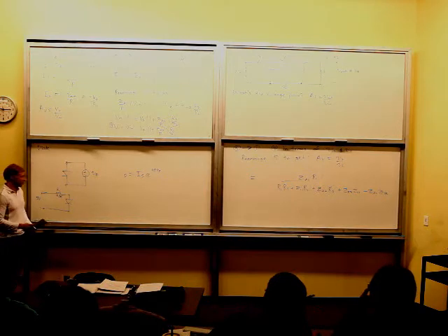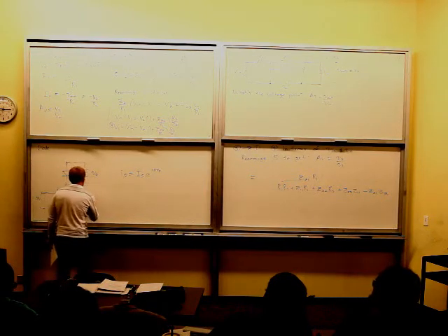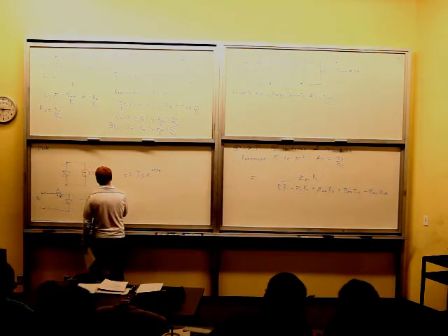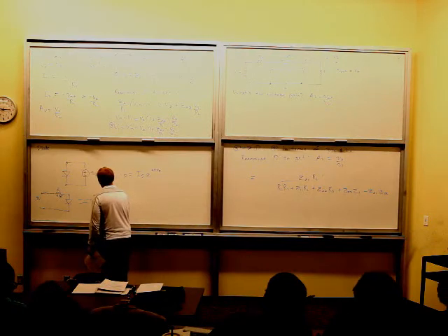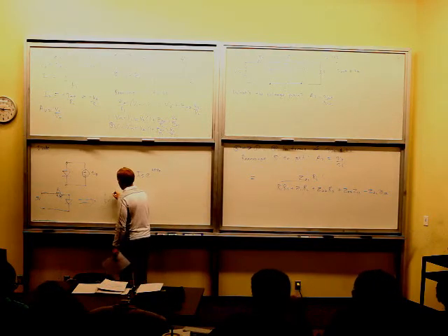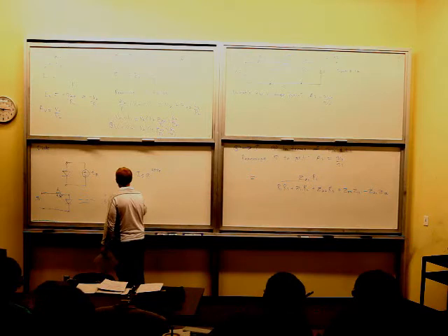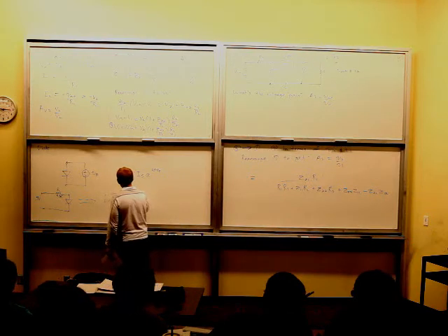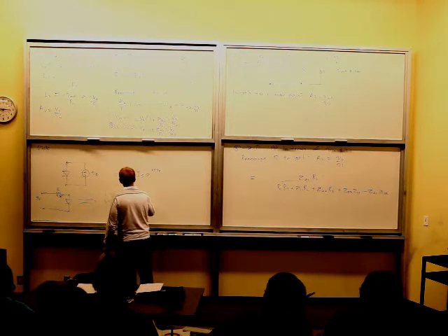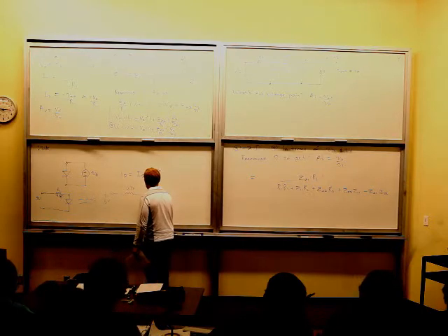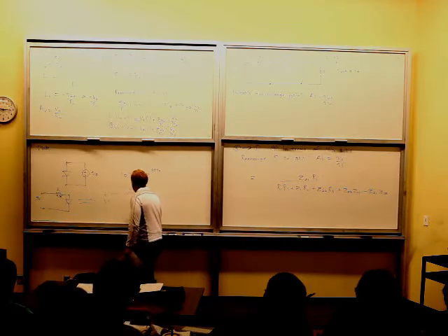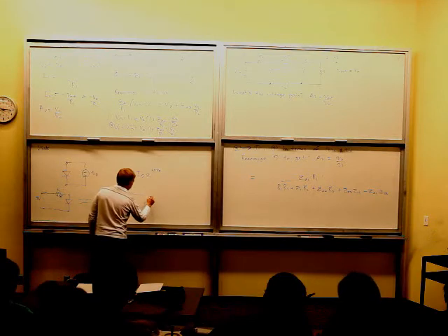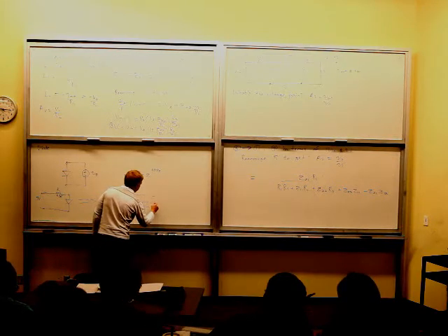In a case like this, you can just say, here's 5 volts, and this is just like what we were doing for the BJT when we forward bias it. There's 4.3K. I'm just going to assume that the diode is 0.7 volts.